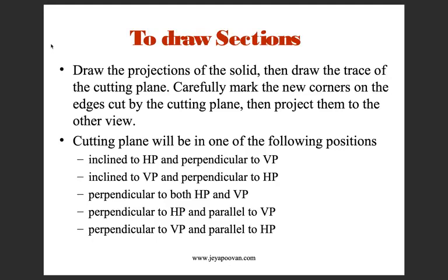The cutting plane will be in one of the following positions: inclined to HP and perpendicular to VP, inclined to VP and perpendicular to HP, perpendicular to both VP and HP, perpendicular to HP and parallel to VP, perpendicular to VP and parallel to HP.